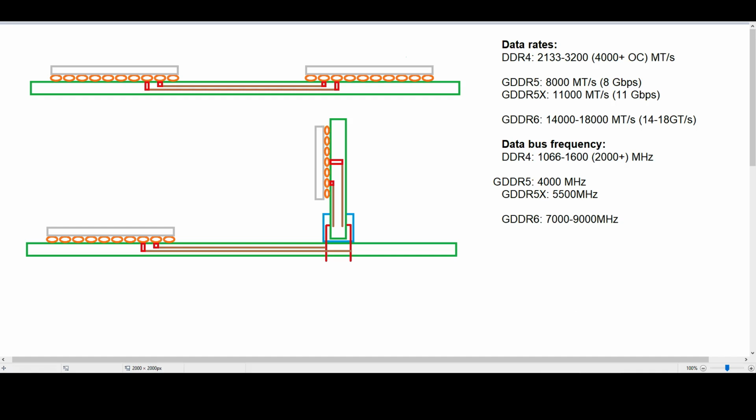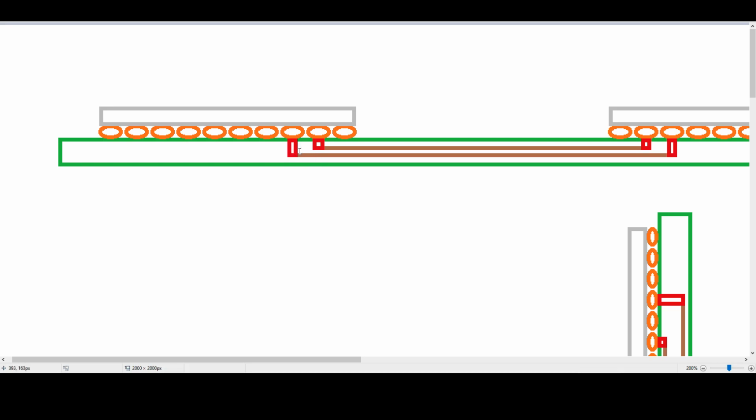And so in the top case here, where we have the PCB in green, we have the conductors, the wires within the PCB, which are here in brown, and then we have the red. These are columns in the PCB, or vias, where we have a vertical connection. So say if we want to go to one of the deeper layers, we need to basically drill a hole. It's not actually done with a drill, but we drill a hole and insert a piece of metal in there, basically, so that we can get down to the lower layer.